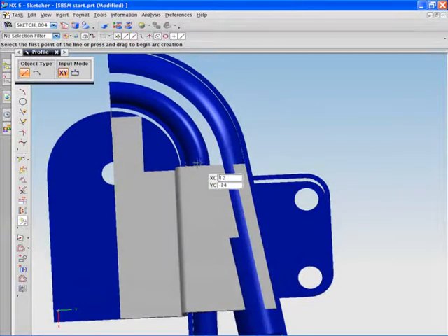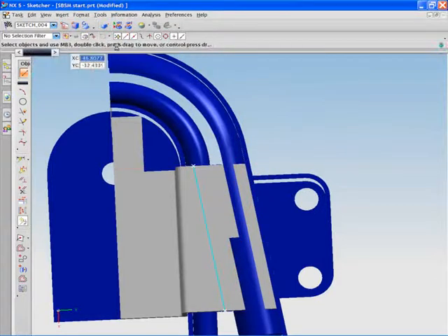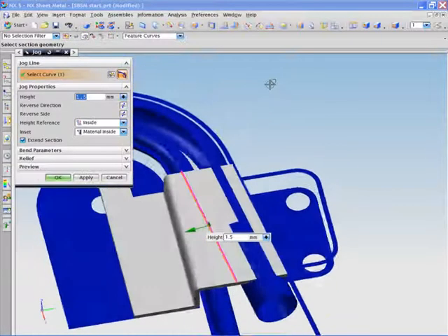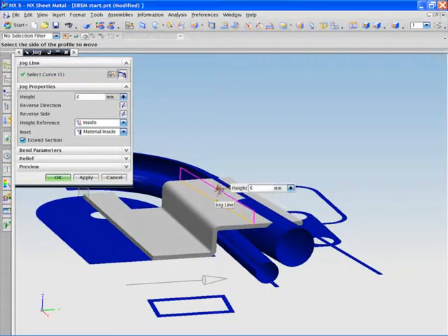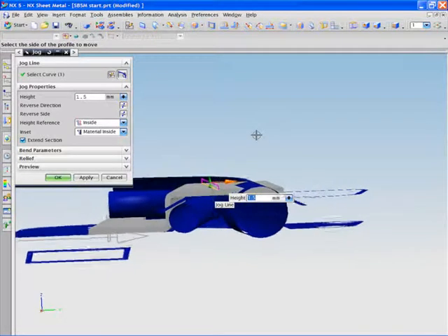You can see that there is still an issue with this flange. Although it is reflecting the profile needed, there is a clearance problem. In this situation, the designer again references the surrounding geometry whilst creating a jog. You are seeing how quickly and easily this task is accomplished.